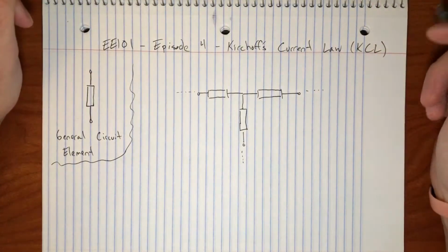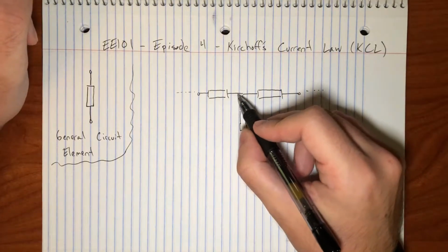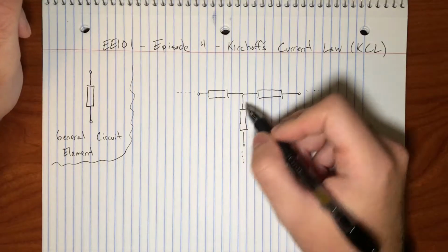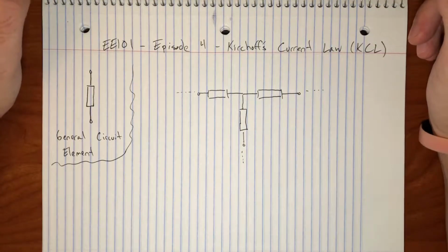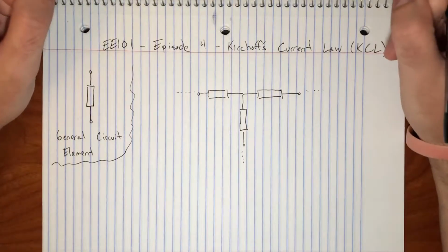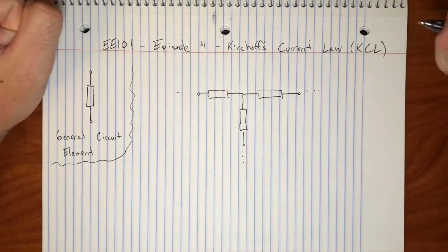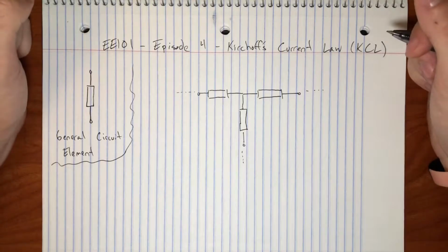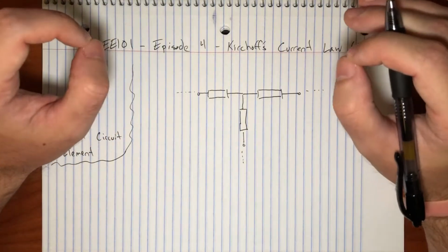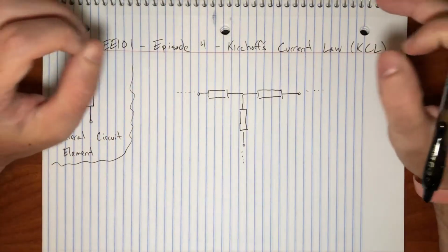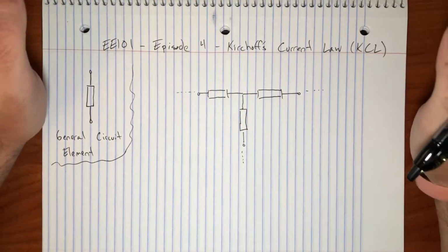Okay, now with that out of the way, when you draw lines like this to connect circuit elements in a schematic, they're basically behaving as ideal conductors. And so what's an ideal conductor? Well, an ideal conductor is a circuit element or a material that has no resistance. And again, I'll talk about resistance in a later video, but another way to think about it is that a conductor in your circuit, as current flows through it, has no voltage across it, ideally. A perfect conductor, which doesn't exist in real life, would have no voltage across it despite the fact that current flows through it.